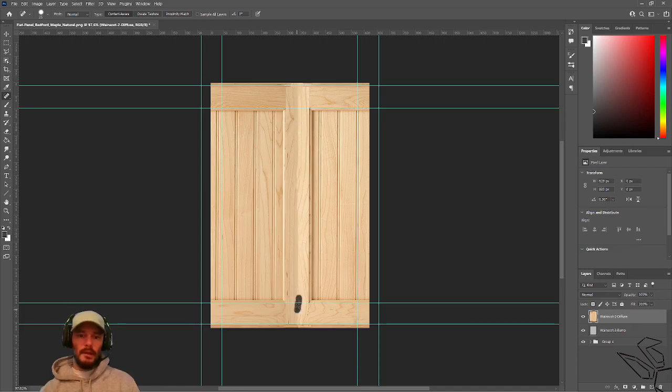We still have some color variation, so maybe I want to move to a clone stamp tool. This is all part of it. Now I can usually do this texture in about 20 minutes without having to explain it. So as you get better at this, it moves along rather quickly. So all I'm doing is cloning from there. I might hit the number 3 key to change my opacity to 30%. And then I'm bringing that clone over just a little bit.